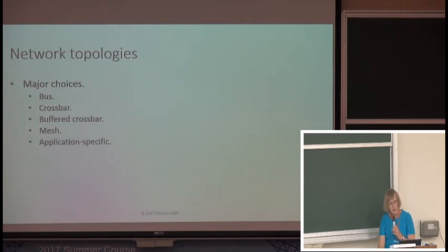We saw that you need a network in order to connect up these elements, right? If we had entirely fixed connections, the FPGA interconnect would be fine. But we can't change the FPGA interconnect on every clock cycle. We need to design a network that can change from cycle to cycle.